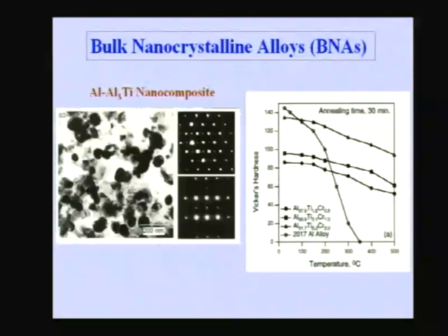The moment you order it, the structure factor changes, and from the structure factor one can really prove that you can see the 100 and 110 reflections as superlattice reflections in an FCC structure. Similarly, in a BCC structure, you don't usually see the 111 peak under normal conditions if it is a disordered structure. Once you make a BCC into ordered BCC, then you can even see the 100 and the 111 peaks in a BCC. Here is an ordered FCC structure, and all those faint spots that you see are the superlattice reflections.